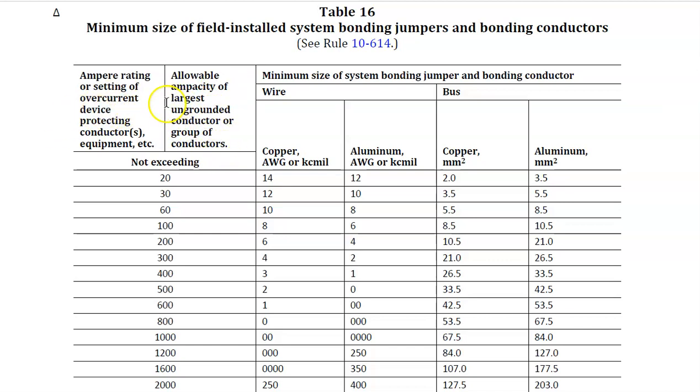Either it is the cable size, or it is going to be the overcurrent size that's going to be ahead of it. And that's just because the larger the cables, maybe they're upsized to deal with voltage drop or something like that, the larger the cable is going to be, the more fault current you're going to be carrying along it. All right.